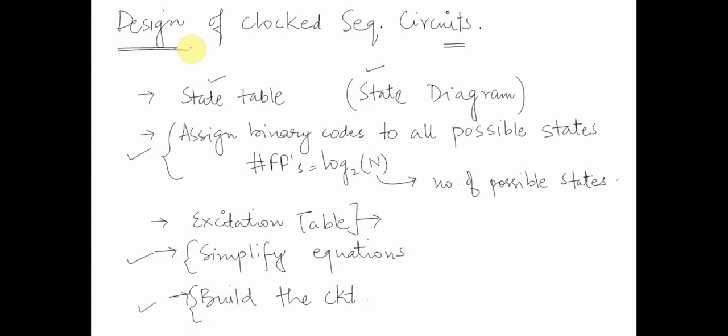The design example we will be taking here is a sequence recognizer. So let's look at what a sequence recognizer is. A sequence recognizer looks for a special bit pattern in some input. It has only one input, x. One input bit is supplied on each cycle of the clock, and depending upon the number of input bits, it will require that many clock cycles to scan the entire sequence. This is an easy way to permit arbitrarily long input sequences.